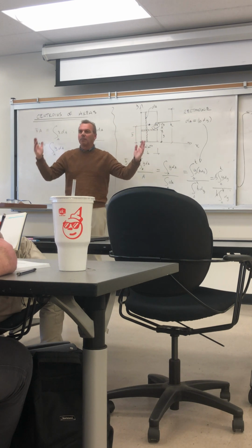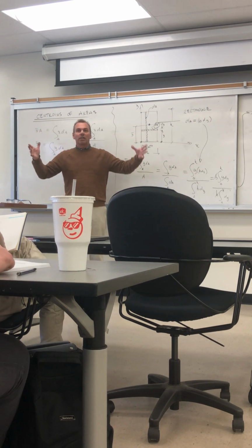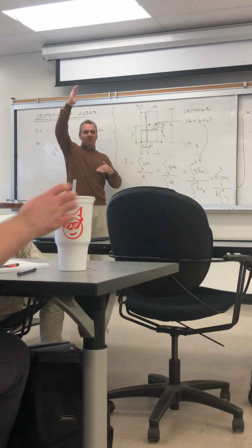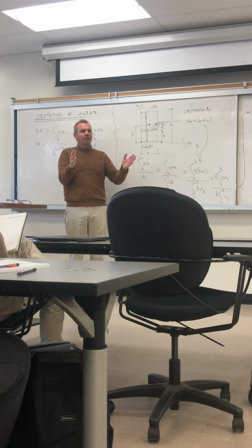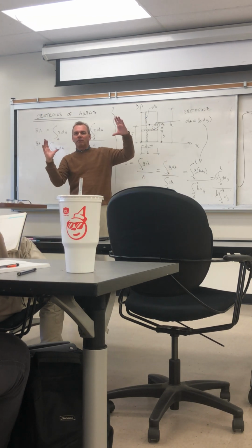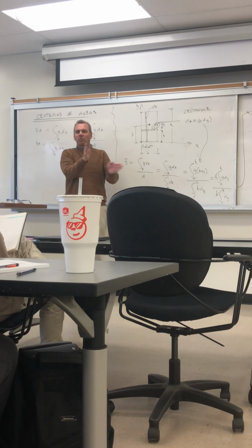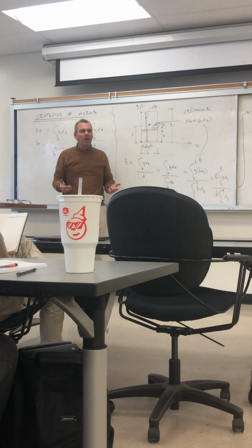But I also warned them they're going to be using forklifts and other stuff, and they shouldn't tilt it. Because if they tilt it, that tall vertical beam that sticks up about 11 feet in the air will lean forward, and the centroid of this thing, when it's rotated vertically, if the back lifts up at all, the front will lift and the centroid will shift beyond the front and the bottom of that steel plate, and the whole thing will topple over. You know, it's over 10,000 pounds.